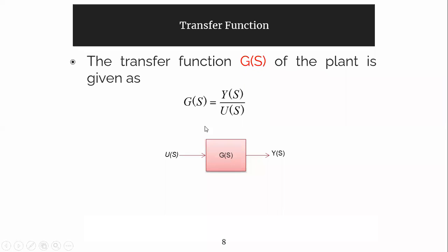Okay, so here we converted to the transfer function by using G(s) of the plant or the network. How can we get it after the Laplace transformation? Initially it was u(t) and y(t) at the initial stage, but whenever you go for the Laplace transformation, the time domain will be converted into the frequency domain. And we can find that the ratio is nothing but the transfer function, which is denoted by G(s).